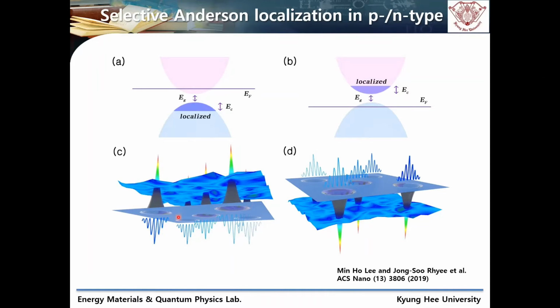In this case, the strong positive random potential allows electrons to tunnel between each other, and on the hole side this random potential can be considered as a random quantum well. Therefore, the strong interaction between the impurities or imperfections and the hole can make it localized like this.